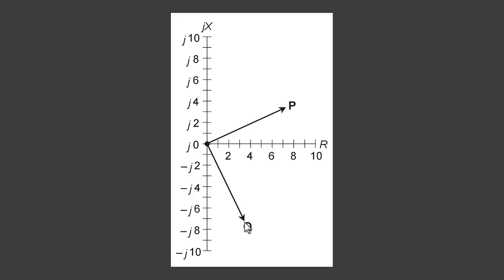If we want to figure out just about how much that is in terms of resistance, looks like about 3.5 ohms, and capacitive reactance about -J7. So the vector would be represented by the point 3.5 minus J7, and the complex number impedance value itself would be the sum of those, or about 3.5 minus J7. But once again, in this question, the correct choice is D.